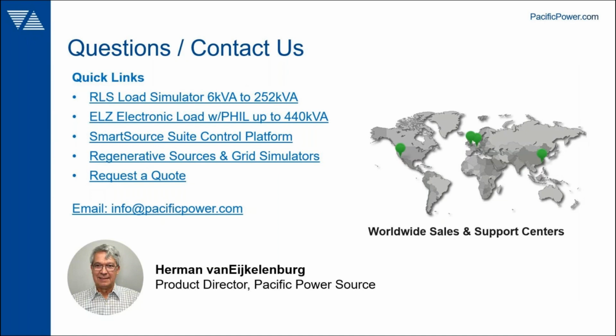But it's a unidirectional, standard, conventional programmable AC source. So it therefore does not have any load capability because that requires that you get rid of that power somehow, and that would require a bidirectional product like the AGX or the GSZ that we used for this demonstration.